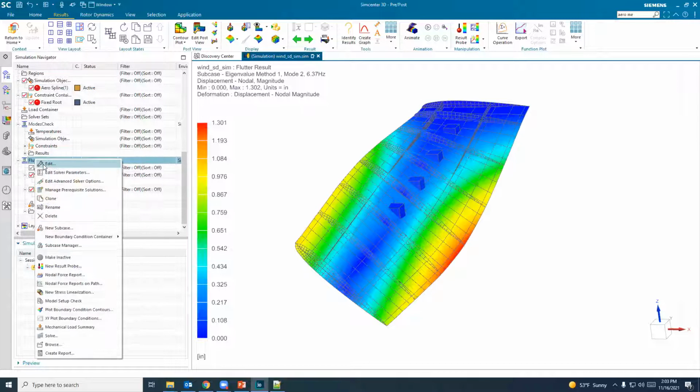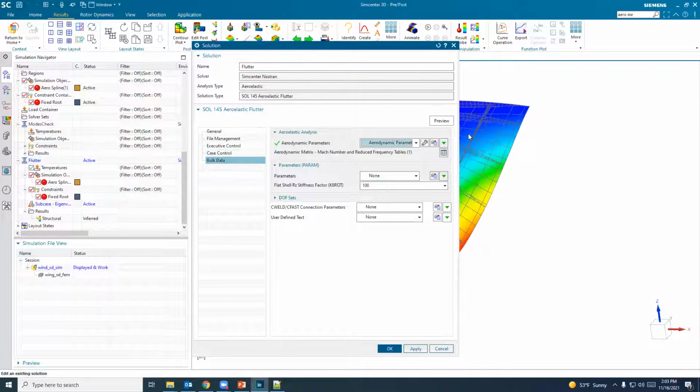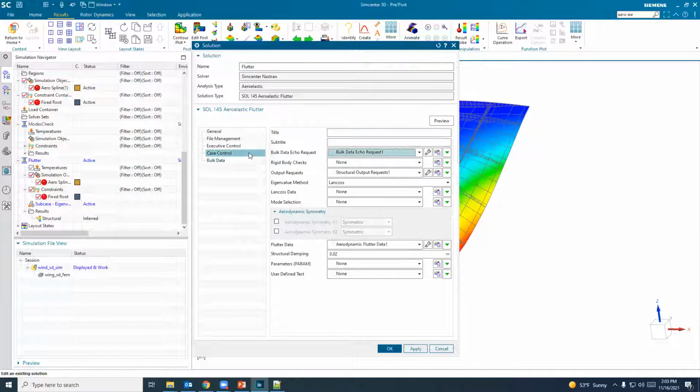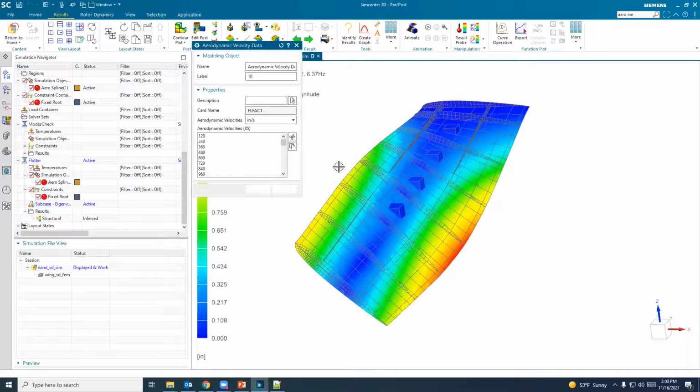So if you do want to look at an aeroelastic mode shape, the way you do that, and this is the way Nastran input works, is in PK method, when you provide the velocity, you provide it as a negative velocity, and that triggers Nastran to compute the eigenvalues for that mode. So that's all we have to do.